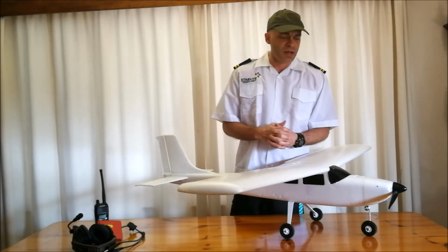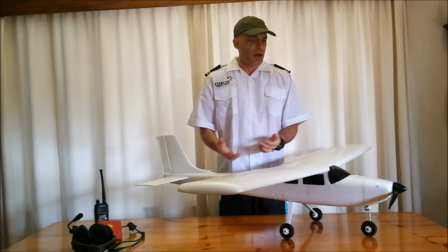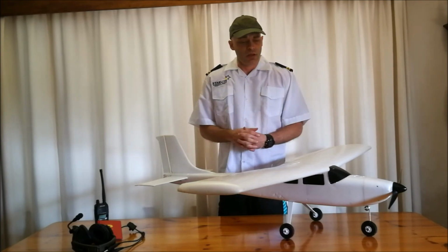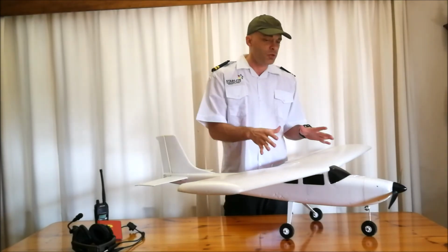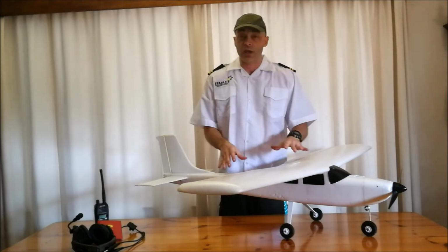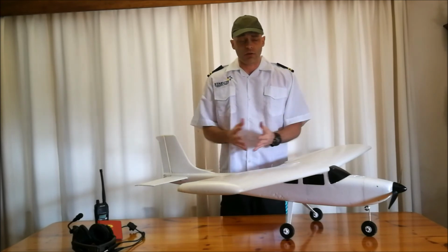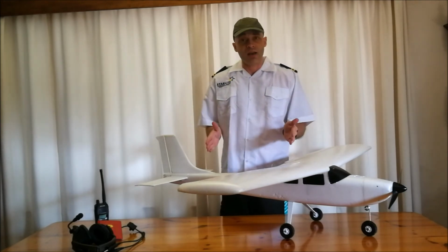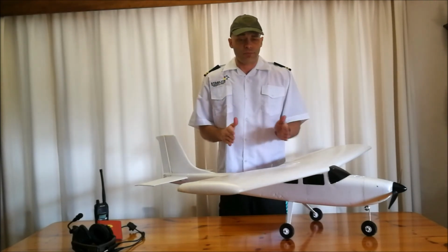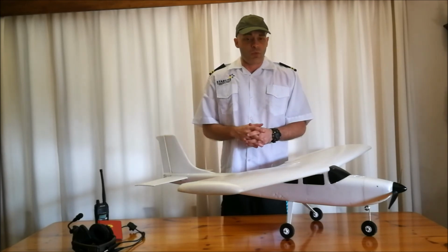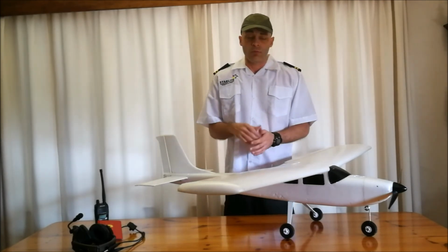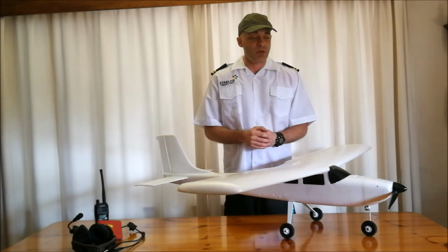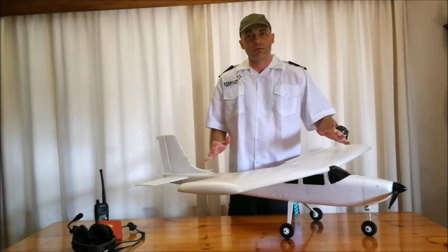Right, so as a manned aircraft pilot, as well as a remote pilot or RPAS instructor, with those ratings we often have to do these weight and balances on small aircraft such as this, as well as a manned aircraft. And if any of those calculations for the mass and balance should be a little bit out of a certain window, then we won't be able to fly. You might be able to take off, but there might be problems when you want to land. Or you might not be able to take off because the weight distribution within the aircraft could be incorrect.